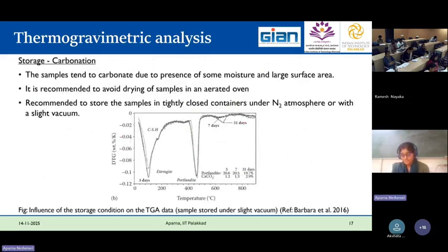It's not only the hydration stoppage technique. Once we stop the hydration, after how much time are we doing TGA? And what is happening in the storage duration? During the storage duration, the carbonation can happen within the sample.